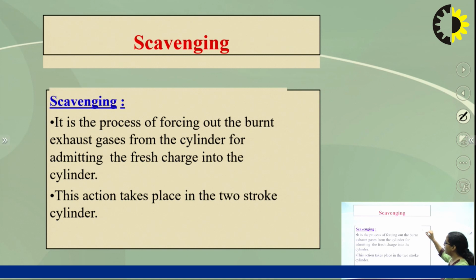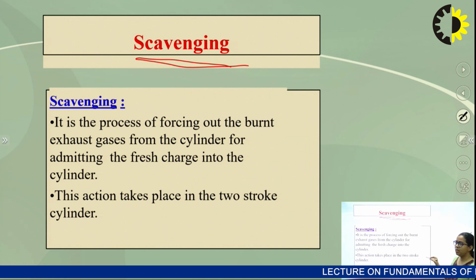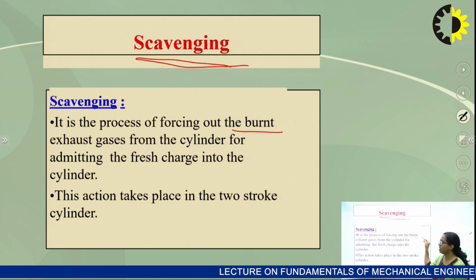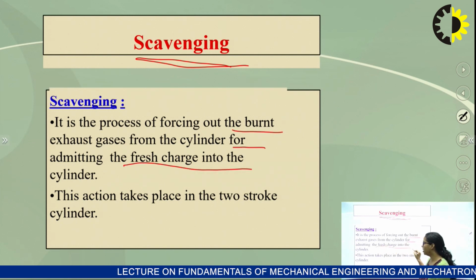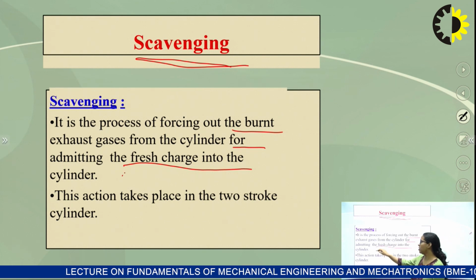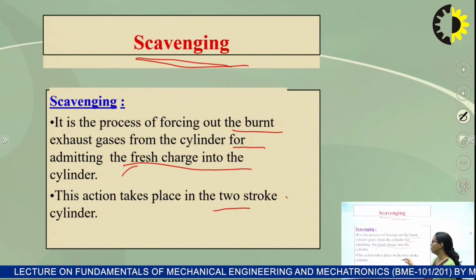Now there is a term that comes in two stroke engine, that is scavenging. Basically, scavenging is the process of forcing out the burnt gases from the cylinder for admitting the fresh charge into the cylinder. This action generally takes place in two stroke engine.